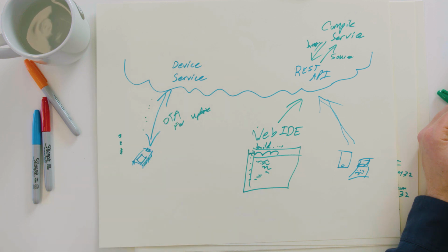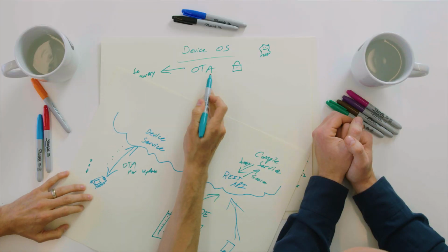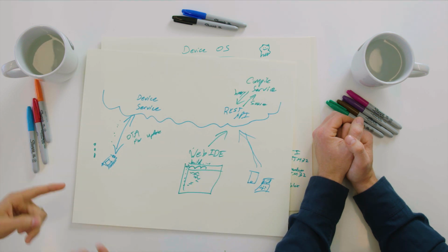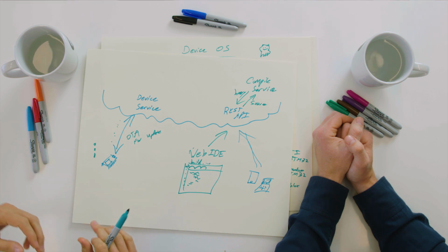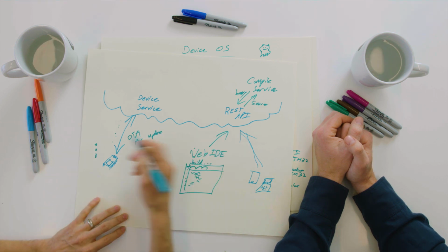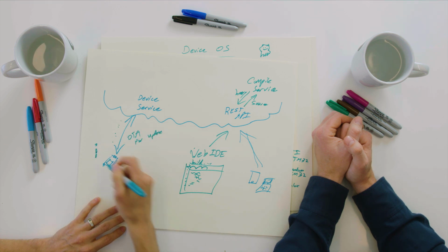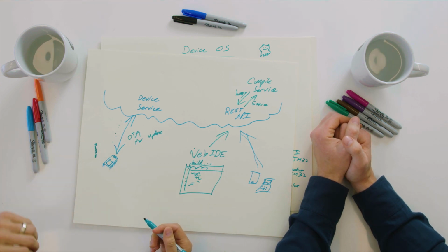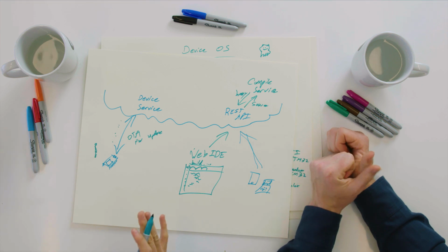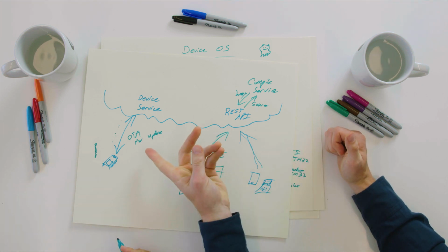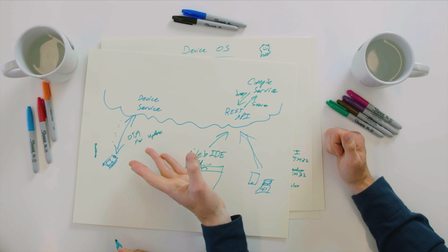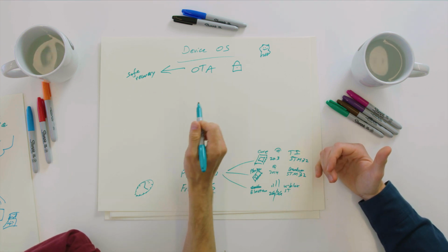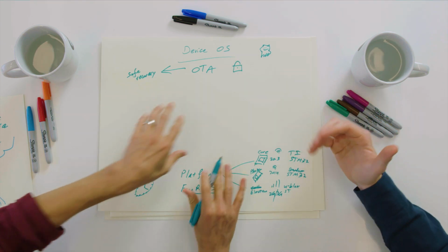When it gets through an iteration, part of what the device OS OTA functionality does is say, okay, at the end of that, I am missing chunks 372, 528, 529, and whatever. It gives a list of the ones it missed, and the device service will send those down. You keep going until everything is saved in flash. Then the device does a full checksum, says it all checked out, and reboots. So the current version of the operating system effectively has the code to evaluate that the new version is going to be safe because it has all the pieces? Or within this OTA module, I guess, rather than the operating system itself.